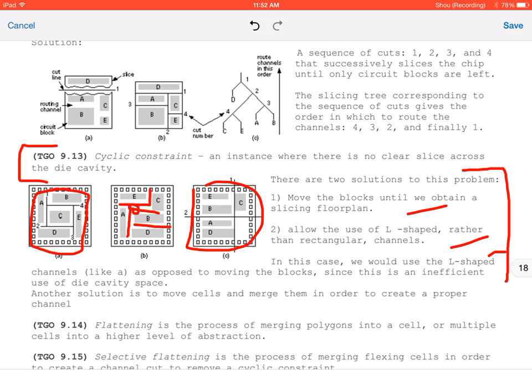Right, so now you have a tree here. This just makes everything the longest possible. Right? So here, B is the compromise. So this is our initial layout. Man, these wires are long. This one, we have a min cut, but this is an ineffective use of the die space because area becomes an issue here. You've got a huge chunk of empty space. Yeah, good design requires good compromise. So this is where B in the middle comes into play.